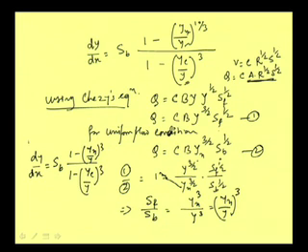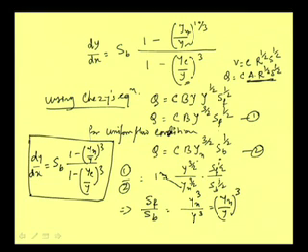So, the expression becomes as simple as this for a wide rectangular channel using Chezy's equation. Okay. So, now for analyzing characteristic of gradually varied flow, we can use this equation conveniently, and that is why we are deriving this equation. Well, now let us start analyzing the characteristic of gradually varied flow profile.